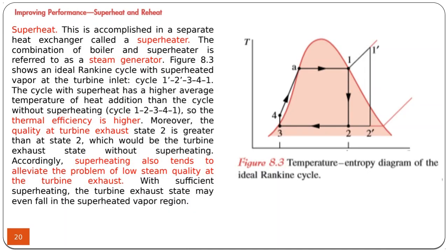Now, up to now, we have studied a vapor cycle which is operated under saturated cases. So it's also possible to have a separate section inside the boiler and to heat the steam over the saturation temperature so that the steam can be superheated. So by adding some more heat, instead of saturated vapor, we can make it superheated by adding more energy to the vapor.